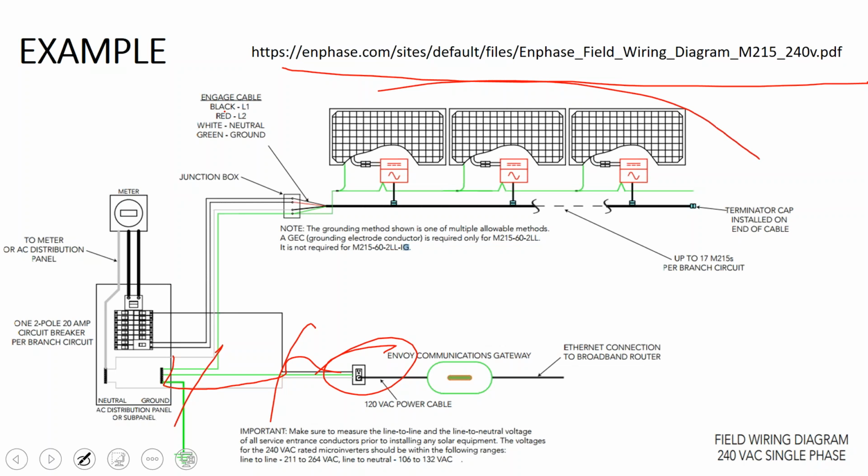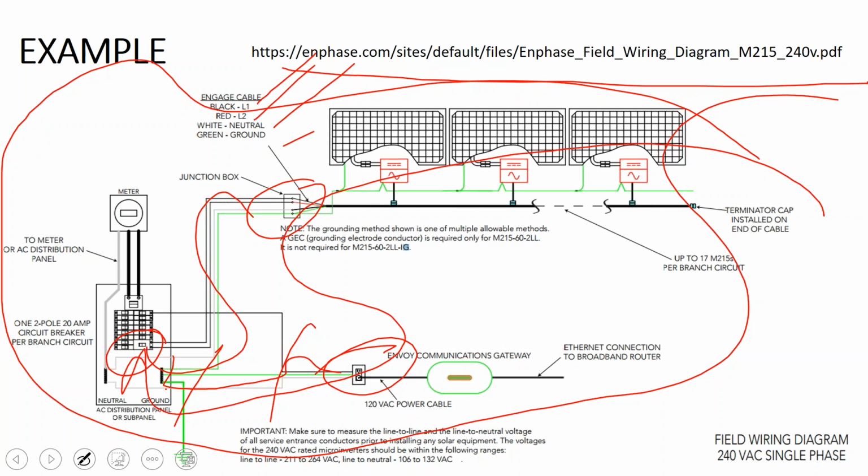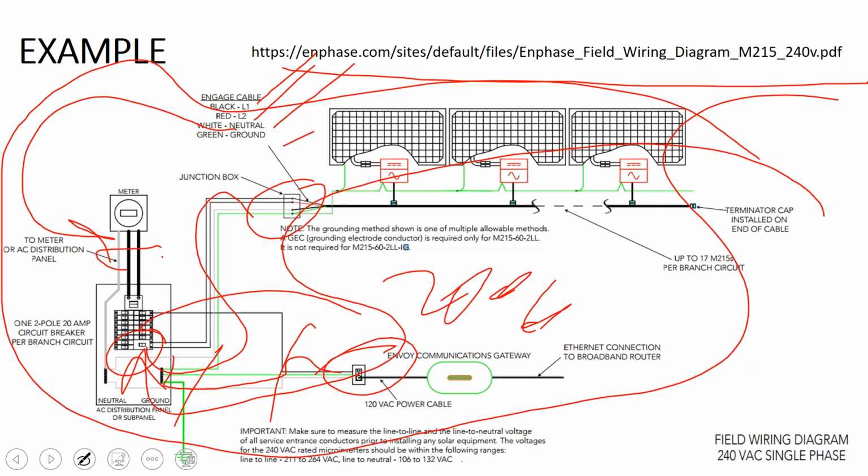You hand them a very detailed wiring diagram that might just be a printout from the manufacturer website, and all of a sudden their eyes light up and they say, well, I've never done solar before, but this looks pretty straightforward. I'm just running a double pole branch circuit up to the rooftop, and I have a leg 1, leg 2, neutral, and ground. Is it that simple? I'm about to get to work. But you'll miss out on nuances like this microinverter is feeding the bottom of the bus bar, and so it's subject to this 20% rule, whereas if you went into the supply side connection, you could do up to 100%.